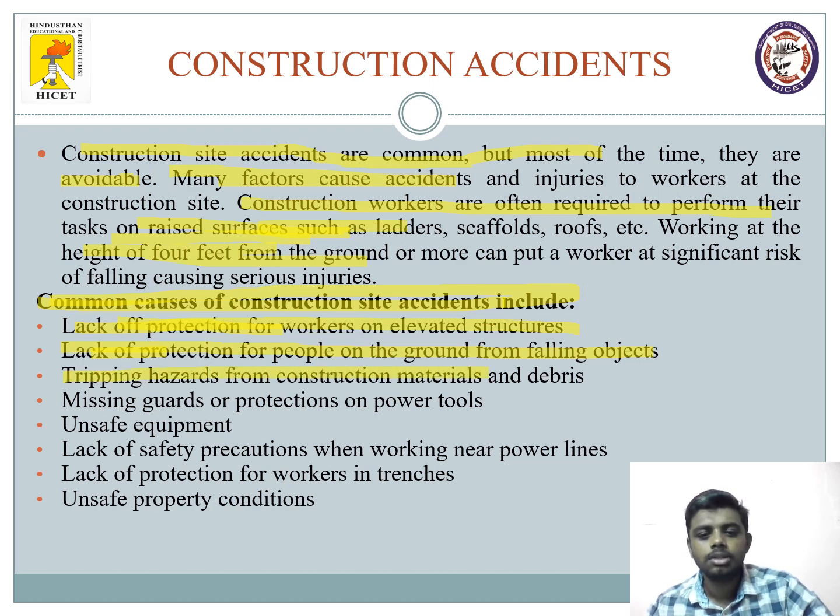Then tripping hazards from construction materials and debris, particularly in demolition work or construction work, where people tend to dump materials in and around the site. So that has to be properly taken care of. If you dump everything in one area, it may tend to fall down or slide, and it may fall on some of your workers who may be working on the lower side of the area. So that has to be totally stopped.